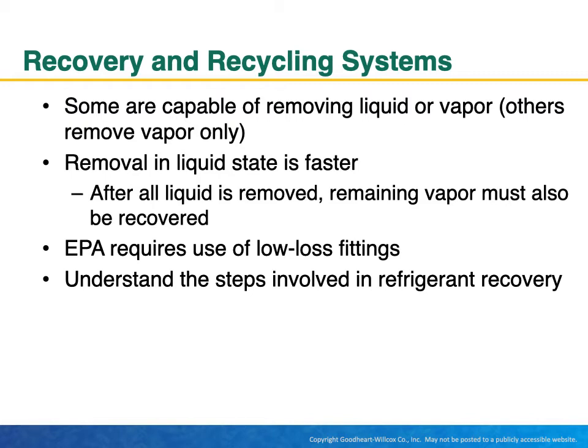Recovery and recycling systems. Some are capable of removing liquid or vapor, others remove vapor only. Removal in liquid state is faster. After all liquid is removed, remaining vapor must also be recovered. EPA requires to use low loss fittings. Understand the steps involved in the refrigerant recovery.